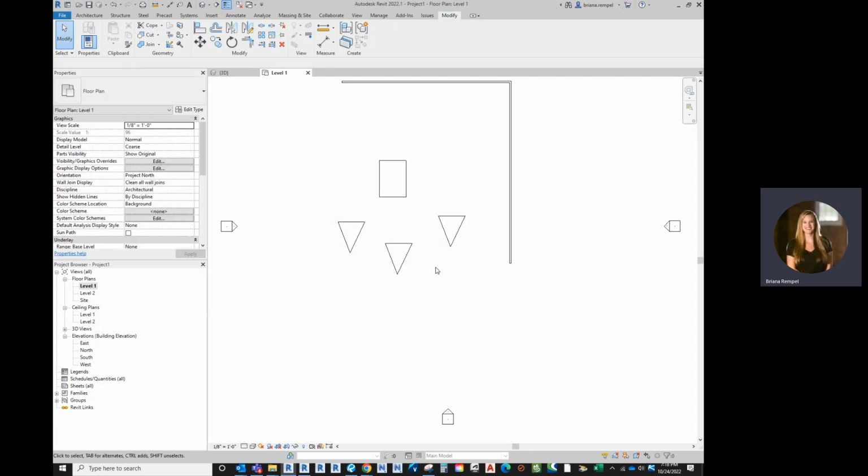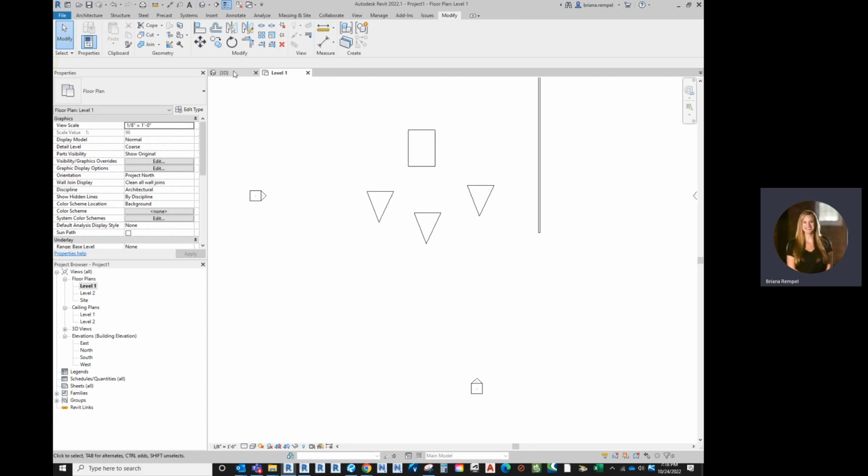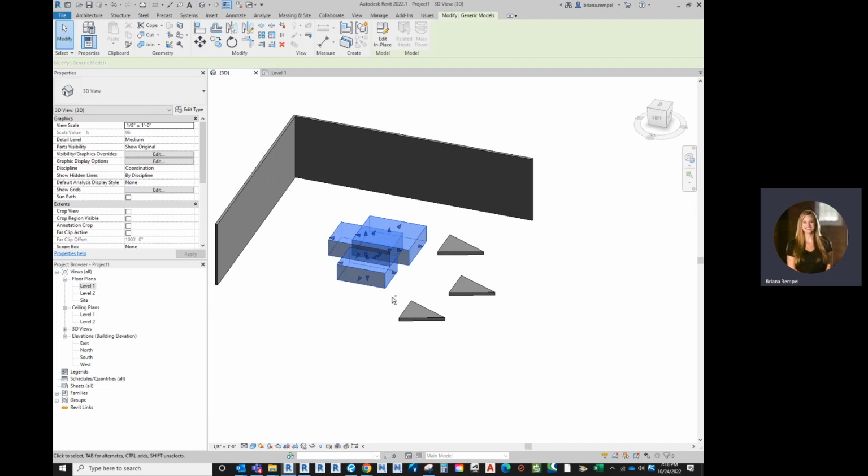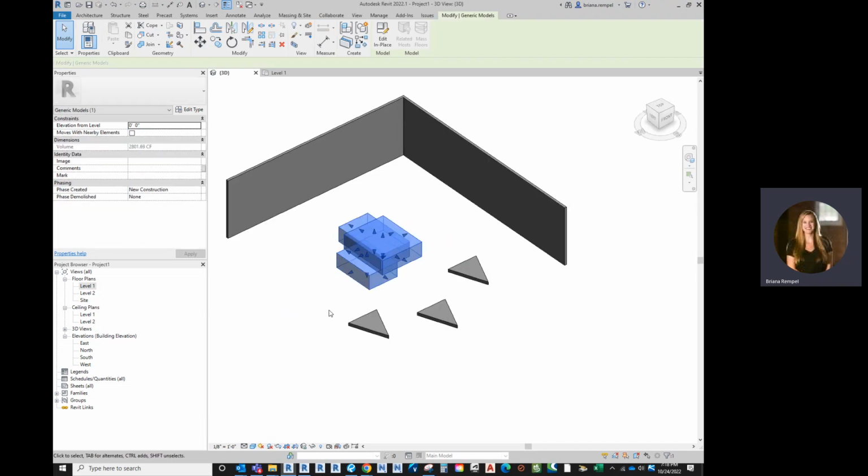That can get a little bit confusing as you start to work in this, but just remember there's 2 levels. First you have your model, then you have your forms. For right now, that is an extrusion, but it also applies to the sweeps, the blends, and these other items that we're going to learn. That's the biggest thing as you start to do this. Just remember that there's 2 levels of sketching for building these: the model level and then the form level.